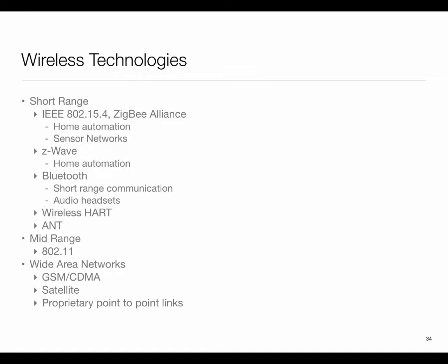An example of the first one, where the sensor acts as an access point and that's the way it remains, is some of the sensors being sold for hooking up to your car, OBD2 sensors which hook up to the port in your car. Many of them are Bluetooth, but some of the Wi-Fi ones basically become an access point. Sensors which are targeting home, like Wi-Fi based weather stations and security systems, usually go through the model where during a setup phase, they act as an access point. You hook up to them through your phone, you give it all the configuration parameters, then they restart, and now they connect to your home network. So that's the idea.